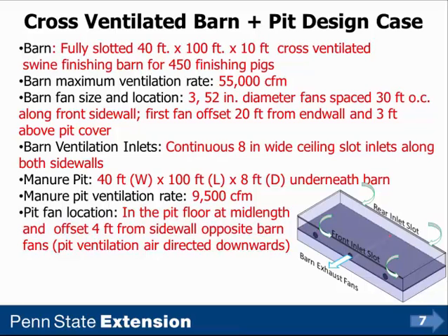The pit fan is located in the pit floor at mid-length and offset 4 feet from the sidewall opposite the barn ventilation fans. And that pit fan directs air vertically downward, perpendicular to the manure pit cover.